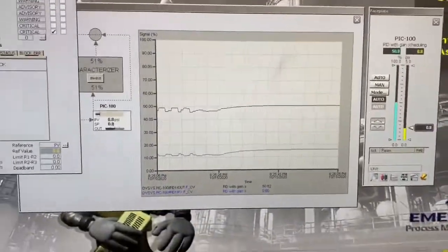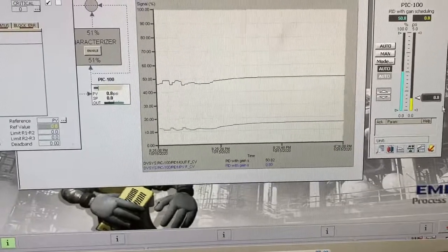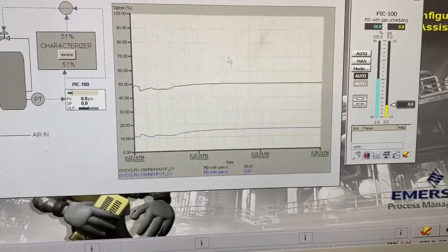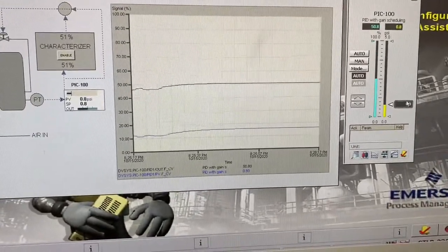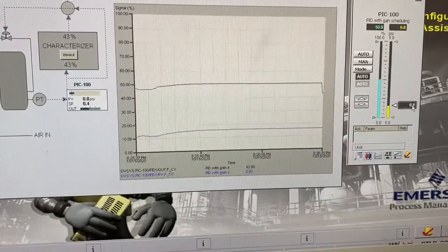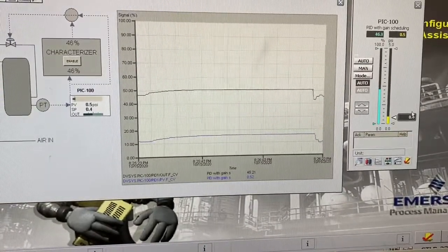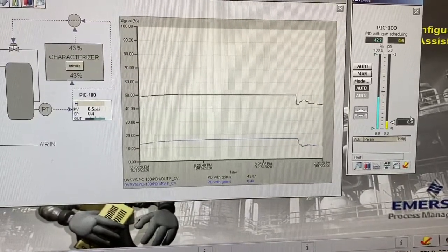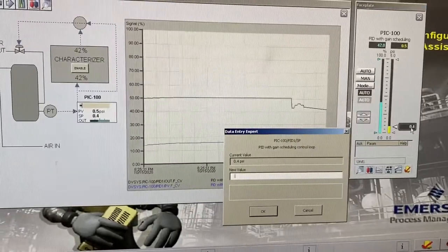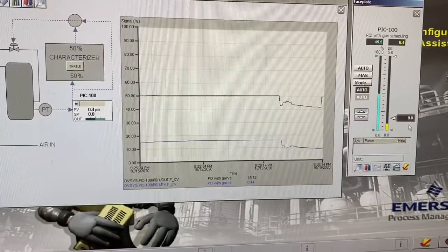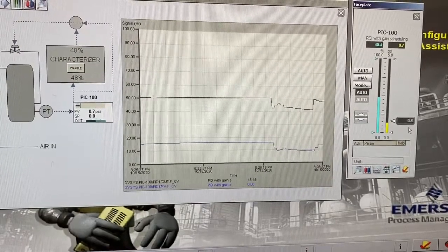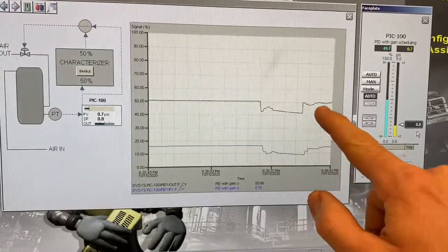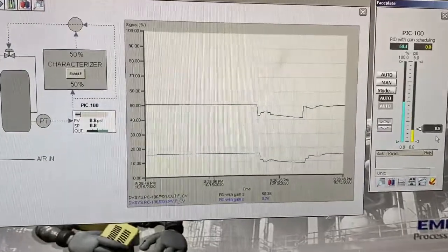All right, so I've entered in our tuning parameters here for a Ziegler-Nichols closed loop for a proportional plus integral controller. And I'm going to go ahead and step this back down to 0.4. So you should see it come down. It should do something like quarter amplitude decay. Looks pretty close. We'll step it back up to 0.8 and see how it does. It kind of oscillates and then stabilizes again. So it looks kind of like quarter amplitude decay, I would say.